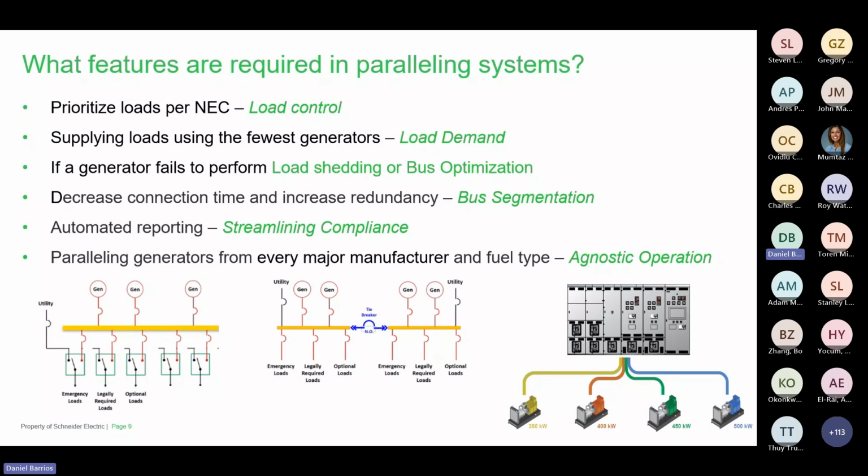Because a 2/3 pitch generator will minimize the third harmonic, whereas, say, if there is such a thing as a 5/7 pitch, it is eliminating or reducing the seventh harmonic. The primary voltages at 60 hertz will parallel, but because of those two differences, you have circulating current. We can attempt to minimize it with our voltage regulation and such. We cannot eliminate it. Complete different topic, but it is something that we would like to pursue with you if we need to explain it better.